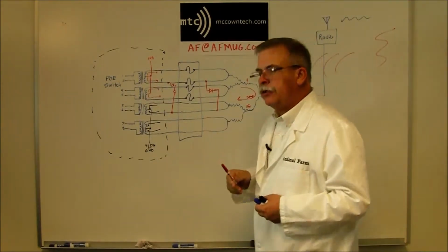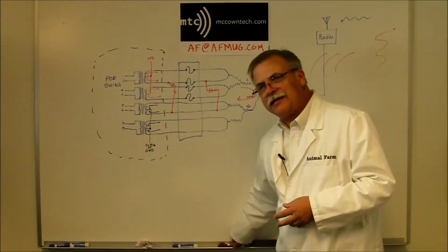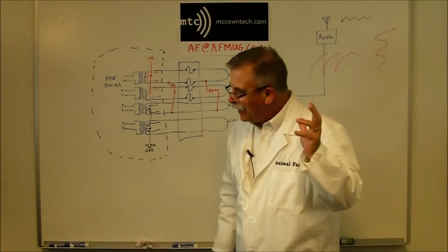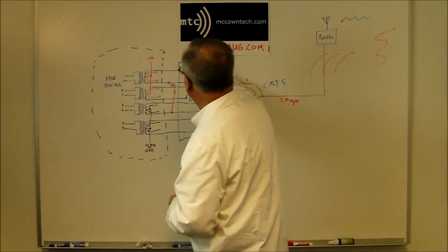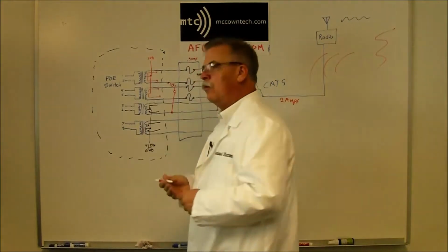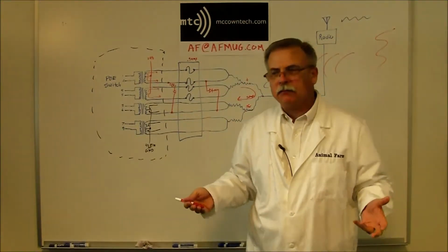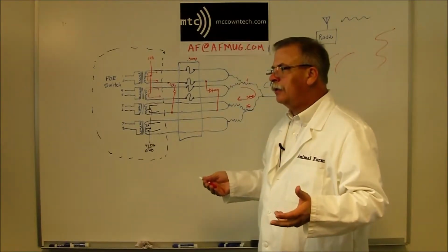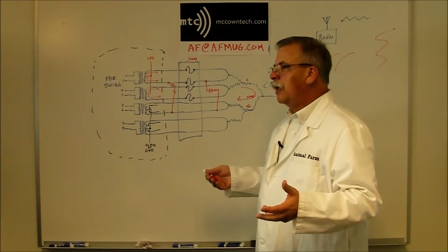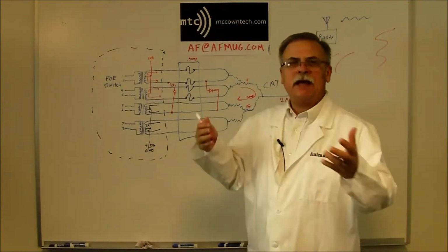So now the problem is, how big should you make the fuses? Well, one would think, okay, again, this is another one of those, one would think that a half-amp fuse would blow at like 0.55 amps. No, not so. It doesn't blow at 0.6 amps. It doesn't blow at 0.7 amps.